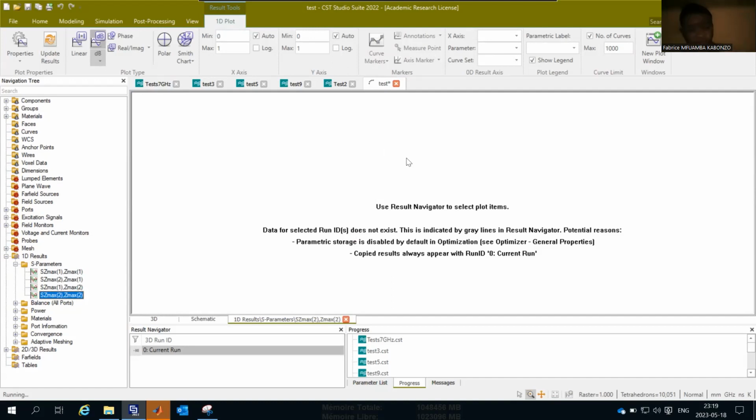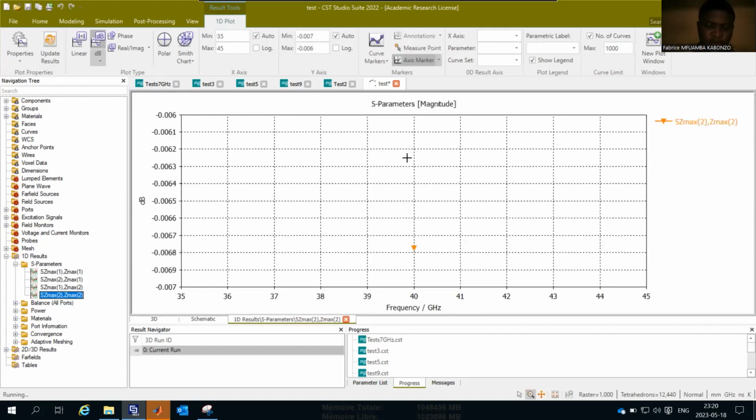Before you go, in 1 minute, he did it. I'm surprised, the result has been removed. He checked different dielectrics, and he said when he increased the dielectric, because the one we used was Rogers 5880, 2.2, increased to about 6, the reflection was reducing to about 0.8. Only the dielectric changed, not the thickness. I can share the parameters on the WhatsApp group so you can see.